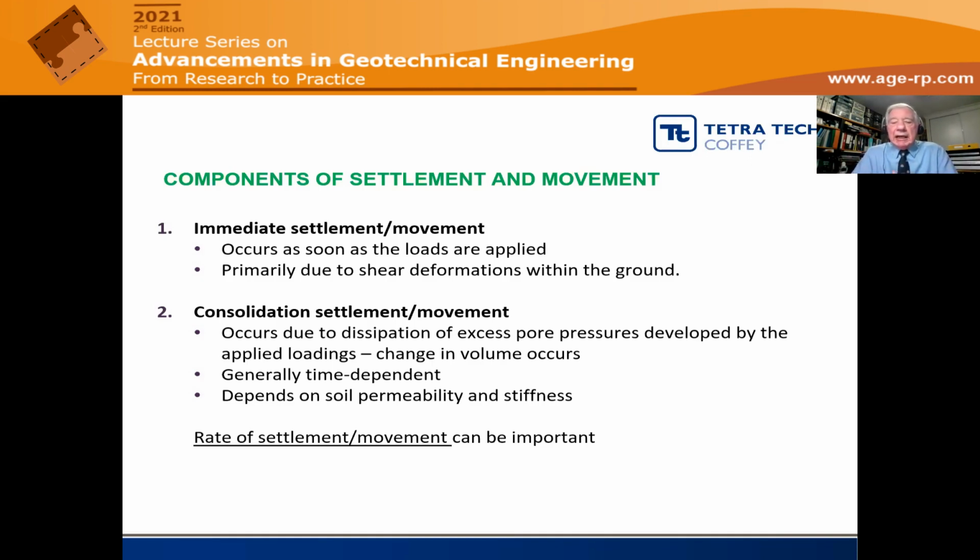So you get a time-dependent settlement, where the amount of settlement depends on the stiffness of the ground. The rate at which that settlement develops depends largely on the soil permeability and on the geometry of the soil profile. So the rate of settlement and movement, as well as its magnitude, can be important, and these are things that we must assess.